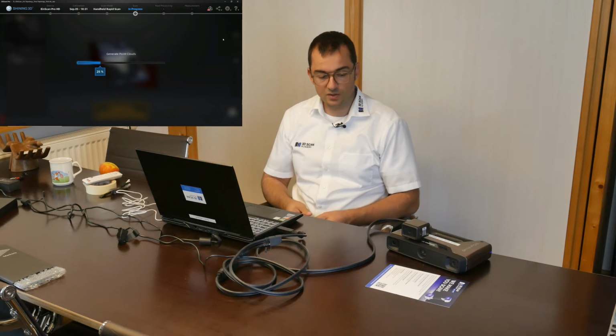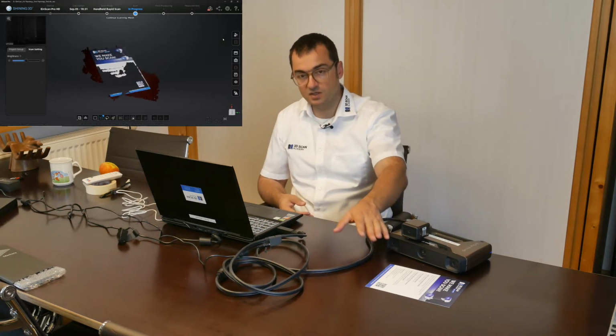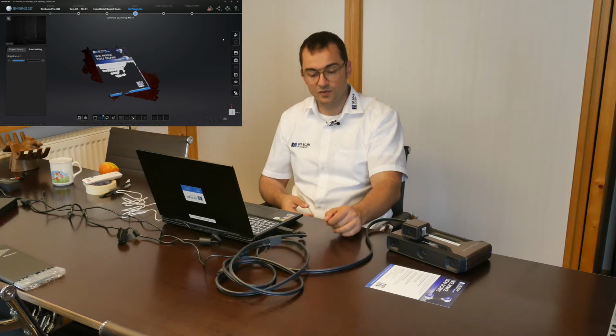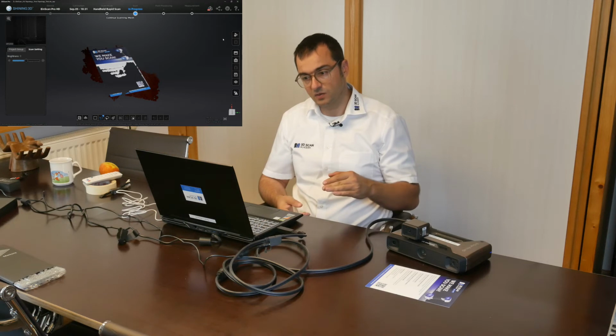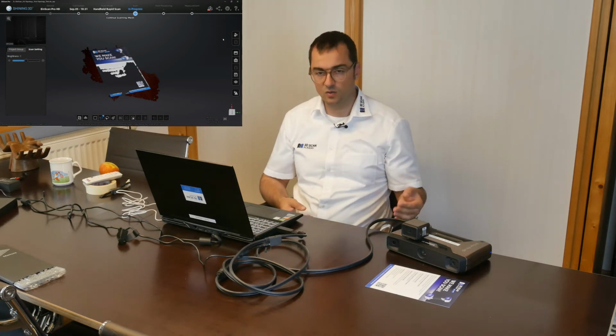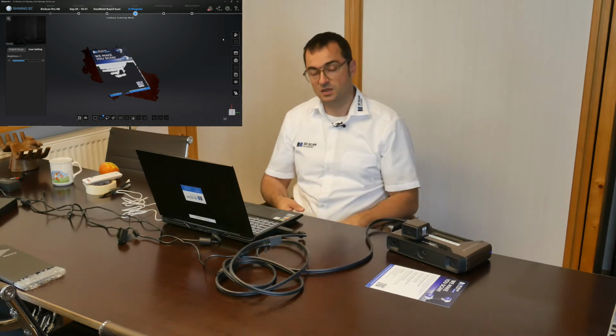This kind of scanner that emits a density of light that will be reflected very differently from the surface will have a problem to scan mixed surfaces regarding surface light properties, because one of them can be out of the range that it can scan, and the other one will be inside, and regulating the one that is outside will kick the other one out of its dynamic range, and you will not be able to scan such a surface.